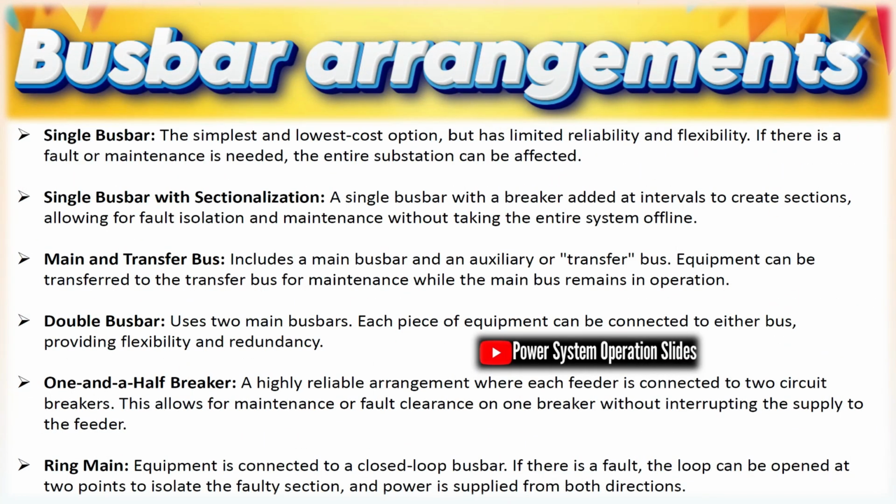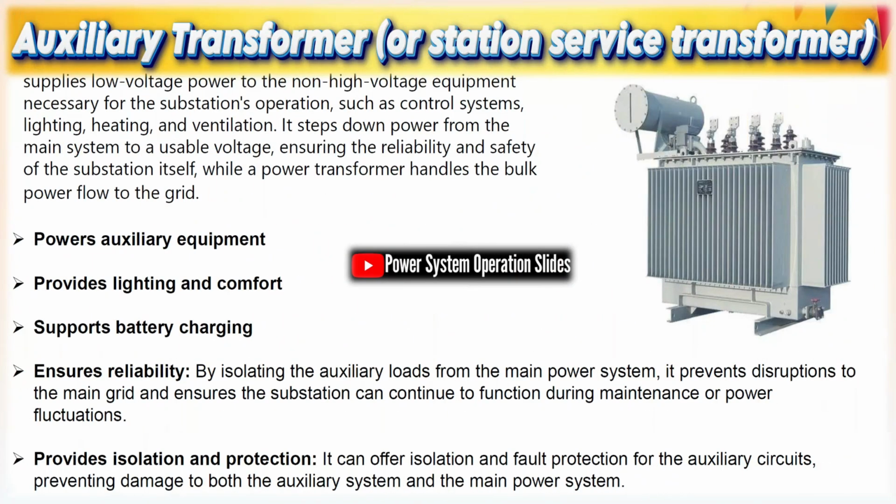Single busbar. A simple, low-cost arrangement where all circuits connect to one bus. It is easy to expand but suffers full outages during bus faults. Maintenance requires circuit shutdowns.